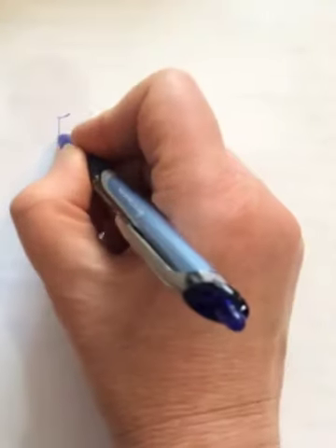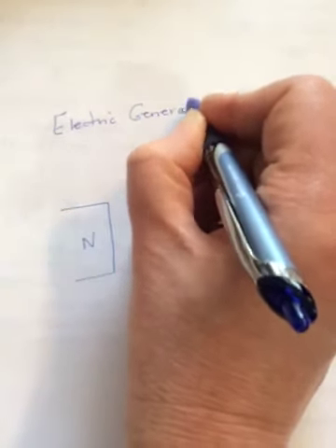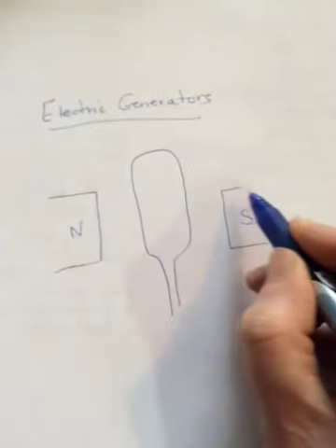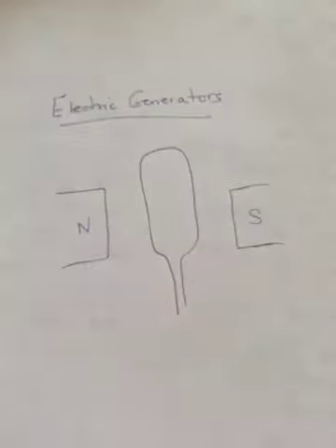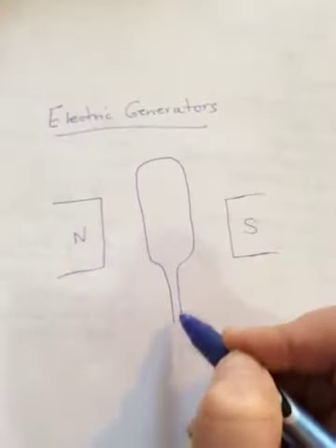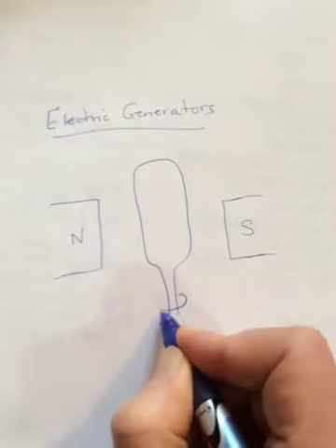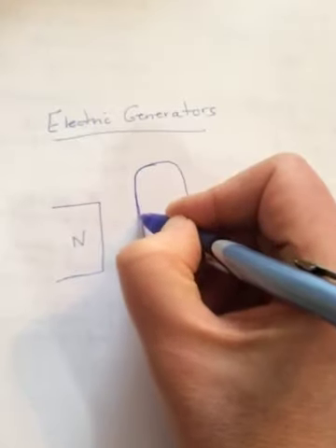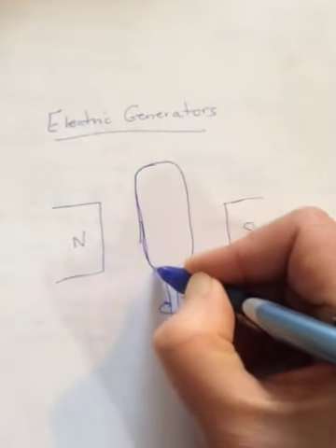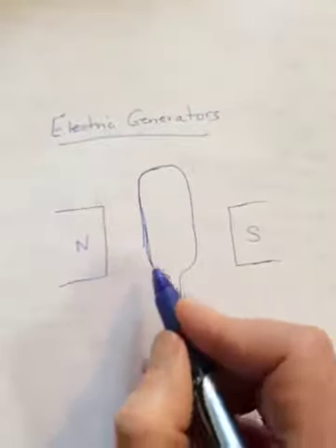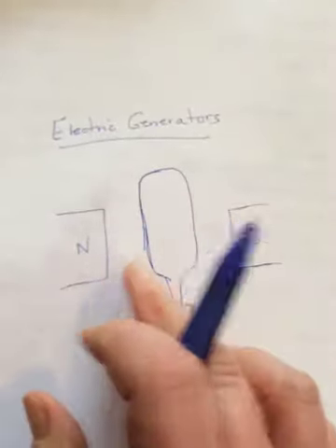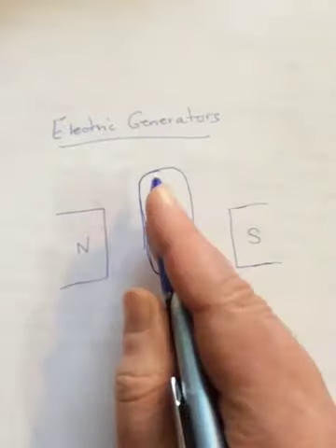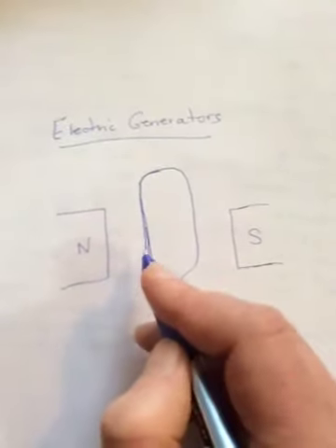We make it by something that's called an electric generator. And I'm sure you've all heard of generators, especially when the power goes out. It's really a very simple principle. You have a big magnet, or two magnets, okay? And you have this coil in between them. And what we're going to do is turn the coil. When we turn the coil, if you just think of this one side of the wire, as we turn the coil, and I have it turning down, going down into the field, it now becomes a wire that's moving in a magnetic field.